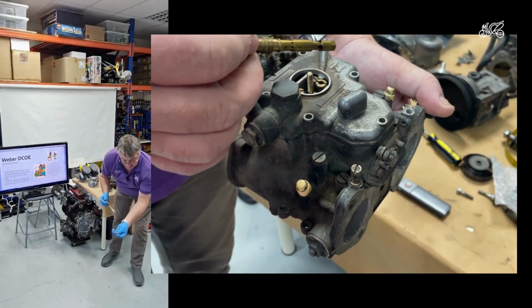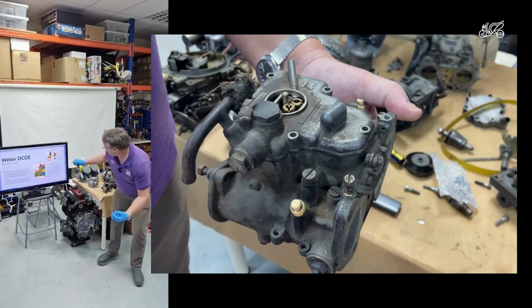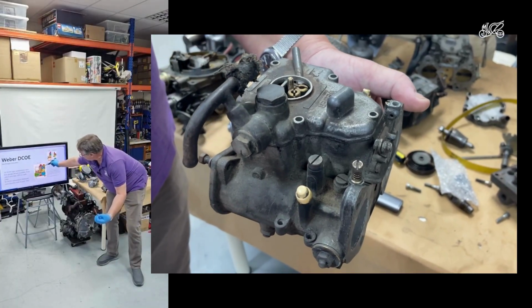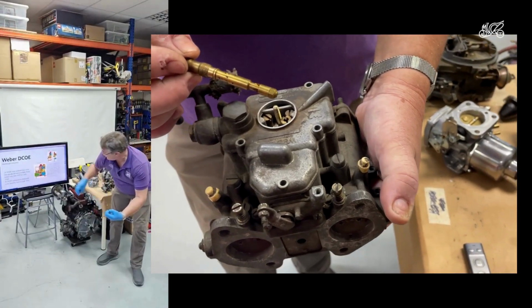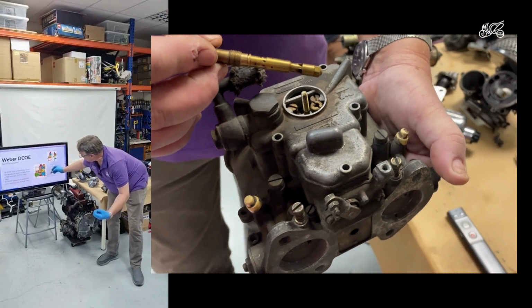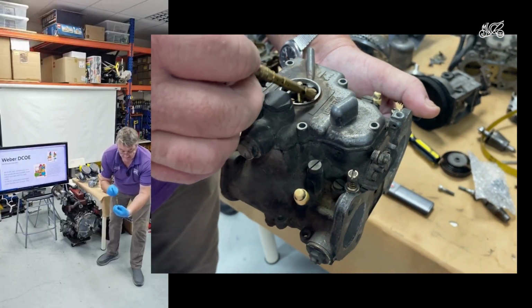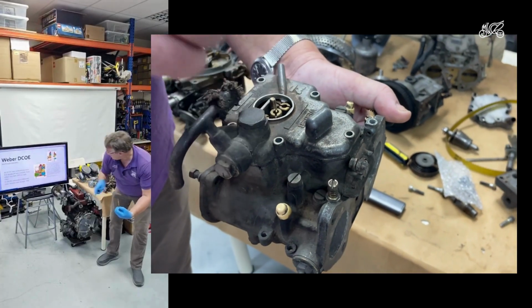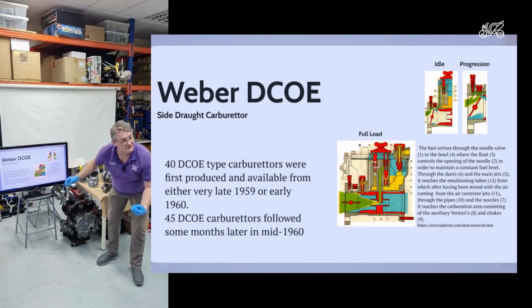So this is the jet, and actually the fuel is coming in at the bottom, and some of the air is mixing with the fuel in this thing. So it's the same pressure as in there, and it's sucking the fuel, and it's mixing the fuel and the air in this thing, and then it's being delivered down this green tube and sprayed into the airflow.